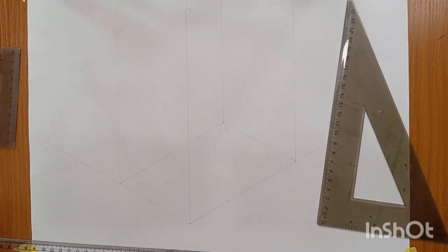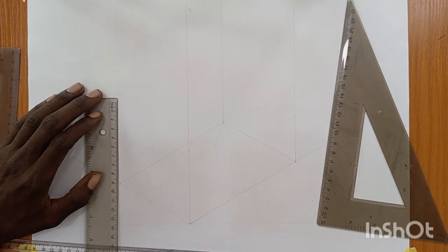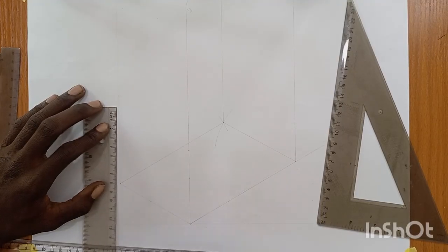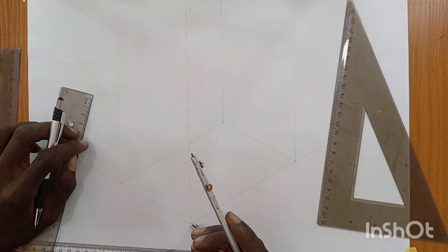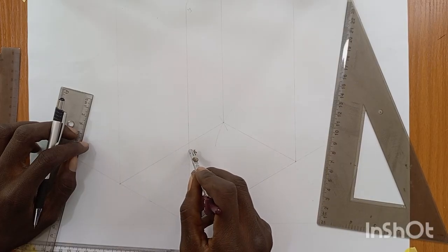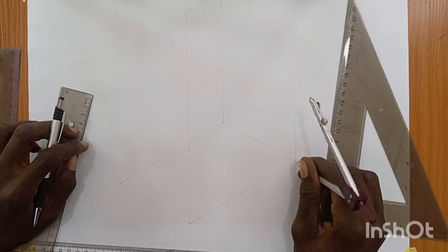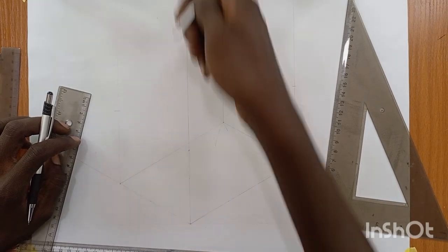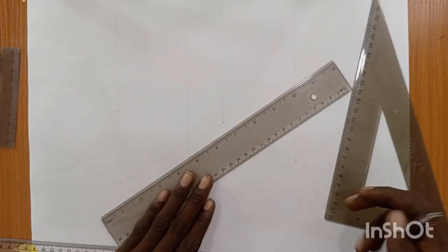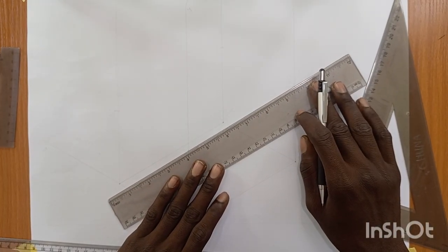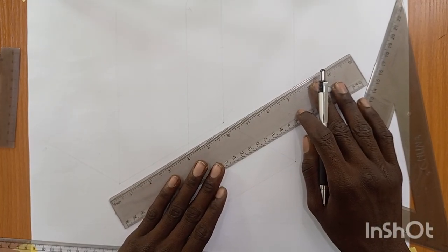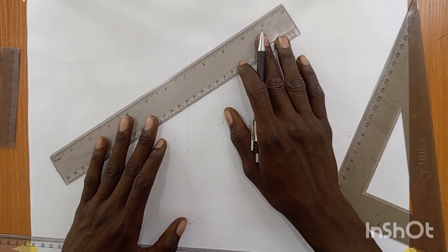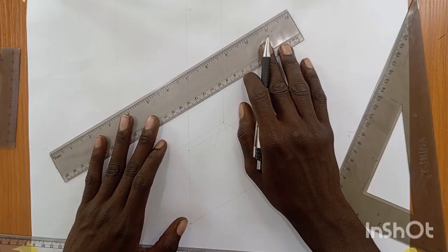Now, in each of the lines, we are going to measure 80. Once we measure 80, we take the height of our bigger cylinder. Now, here we measure 80. Or else, we can use a compass, since we already have the measurement of this one, to make our work faster. So here is 80, right? And then with this, here we strike an arc. 80, here, strike an arc, here, strike an arc. So now we join all the points. Now, something like this. When joining the points, you can use your 30-60 square to do so. And then now join these points, and also these 2 points.